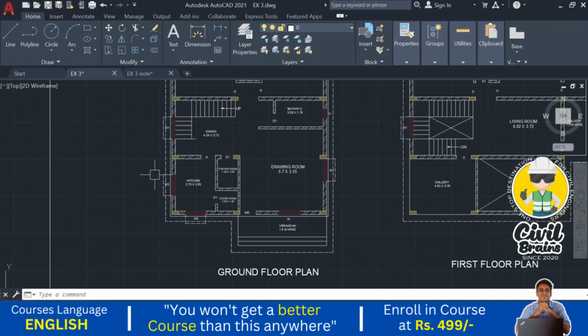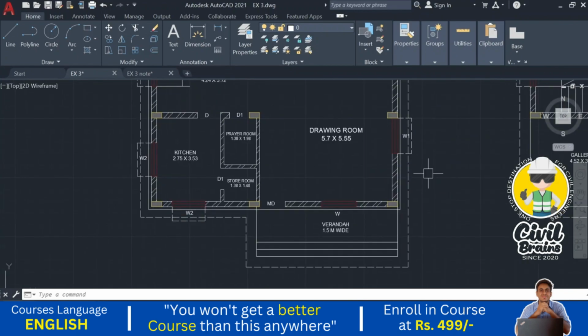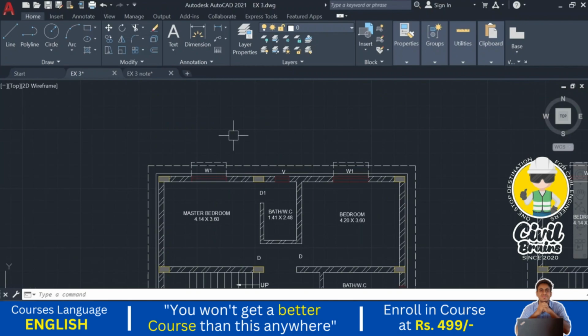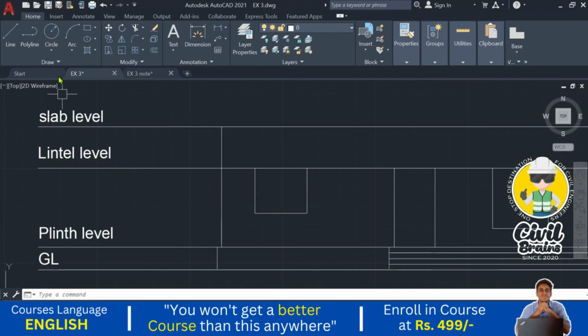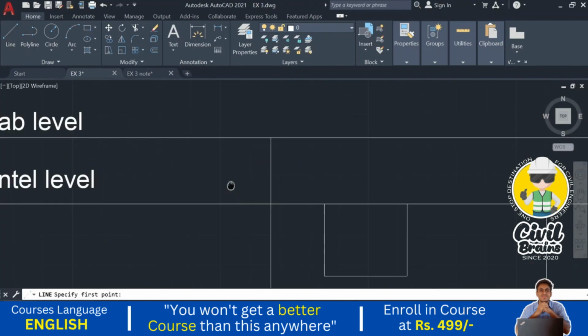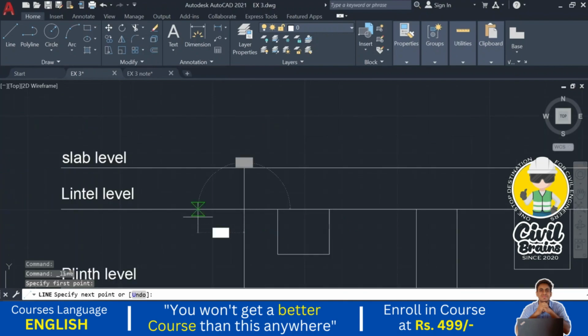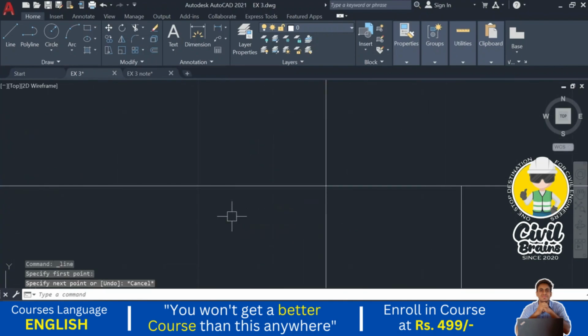Okay, so next, what is visible here? We are just seeing these two chhajjas and the slab projection, right? So this chhajja, W2 chhajja and W1 chhajja. I just draw that chhajja projection here at the lintel level. So I just use the line command. What is the chhajja projection? That is 0.6, or you can project the line from here also, as you know, right?